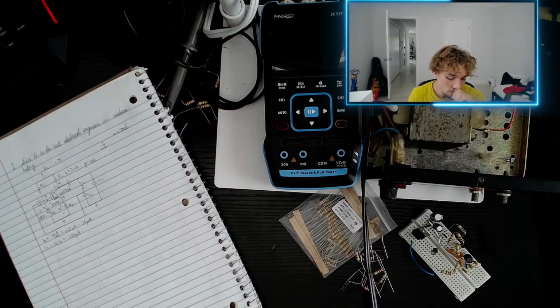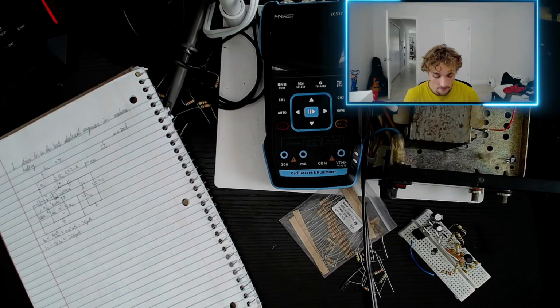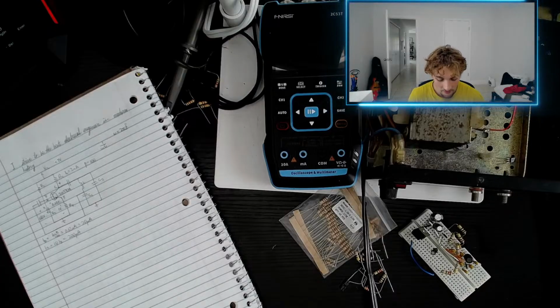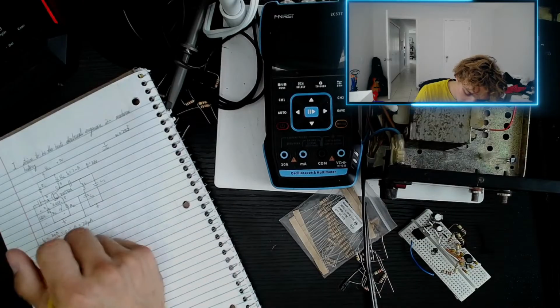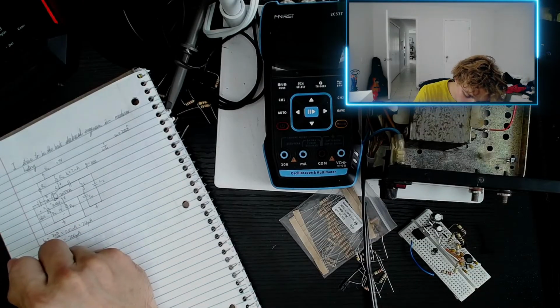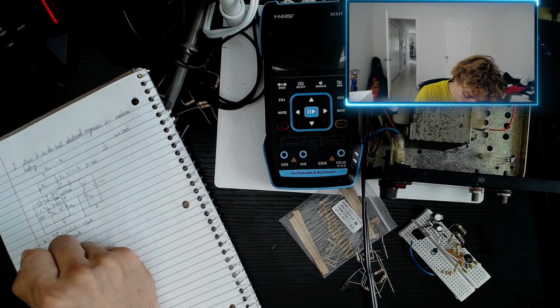Okay, so that's good. So now considering that we have I2 and we have our voltage across R2, we can go ahead and derive the value for R2 through Ohm's law. And that's going to look like this. R2 equals 1.65 volts divided by 200 microamps.